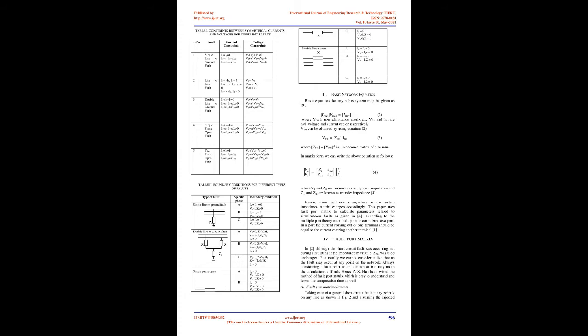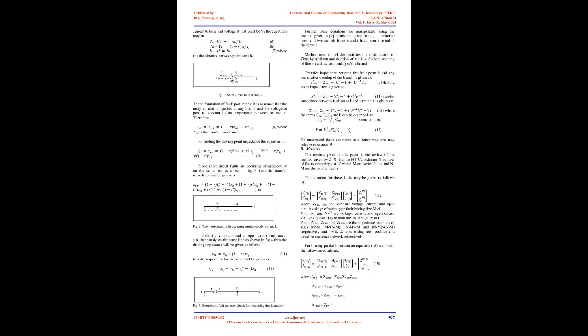Under the normal fault analysis condition, analyzing occurrence of fault on any phase is not a difficult problem, but in case of simultaneous faults, occurrence of faults on different phases has to be considered. Usually, mutual coupling is present between the lines, but that is not considered in this paper. The impedance matrix is to be modified whenever a fault occurs in a system. This is the mandatory requirement while doing fault analysis. This modification can be anything ranging from addition or deletion of a bus as given in 8. The sequence network interconnections are also another important point that needs consideration.